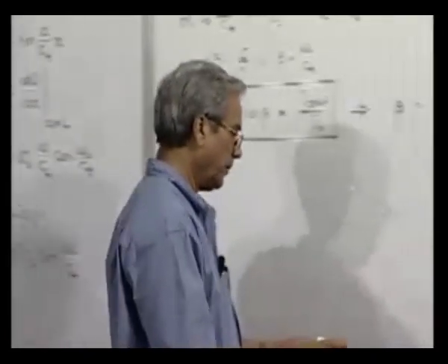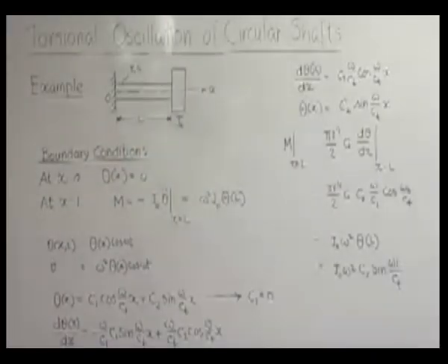So next we take up transverse vibration, but by far that kind of vibration is far more common in machines and structures, and therefore we should take up that in more detail. It is true that longitudinal vibration of bars, etc., is important, but in reality most of the time we get lateral vibration of the structural members. So we come now to the transverse vibration of beams and such problems.